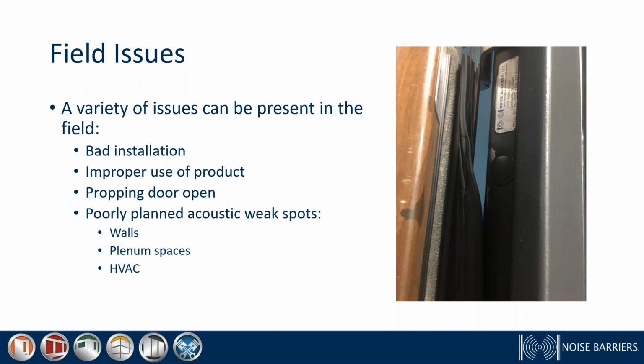And also the seals at the bottom of the door, when you're propping the door open, it can often cause a lot of damage to those and render the acoustic door very ineffective because the seals aren't going to lock in properly. And then also just poorly planned acoustic weak spots. You have walls, plenum spaces, and HVAC areas for the noise to go through.